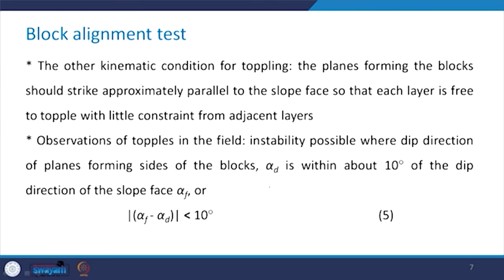The other kinematic condition for toppling is that the planes forming the blocks should strike approximately parallel to the slope face, so that each layer is free to topple with little constraint from the adjacent layers.